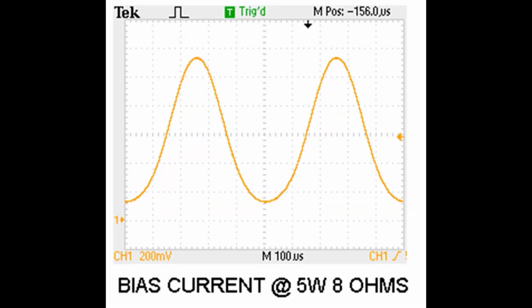As noted, this is a Class A amplifier in which both halves of a push-pull output stage conduct current over the entire waveform without the discontinuities seen in Class B and AB amplifiers. In our final graphic, we see an image of the current flowing through one of the output transistors at 5 watts output. The amplifier idles at 12 watts per channel, but enjoys a generous conduction envelope through the square law character of the FETs.